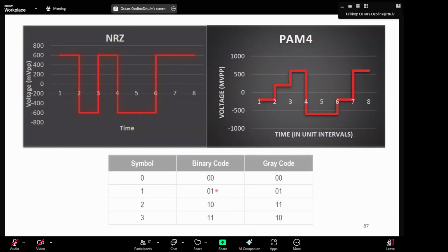So for half of the symbols, your bit error rate compared to symbol error rate without gray coding will be worse, potentially even 50%. So that's why when you do this more advanced signal processing, you also have some freedom, and you can find clever ways to minimize errors. All right, I think this is important to know.